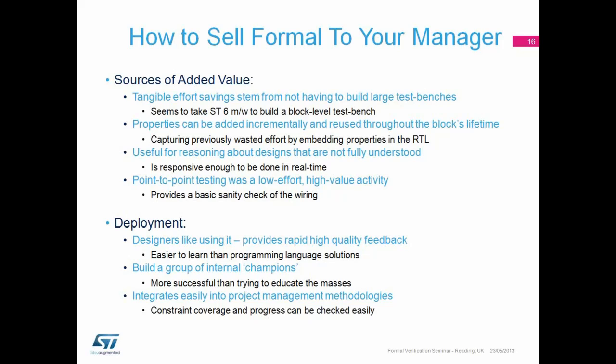The second key point is that properties can be added incrementally and reused throughout the block's lifetime. What we used to do is start off with unit level verification and write an HDL test bench, typically Verilog. Once the block enters verification, it gets thrown away. That effort's lost. At block level verification, we write another, completely new test bench, which when the block enters system level verification gets used a bit for regressions maybe, but that effort really is now gone.